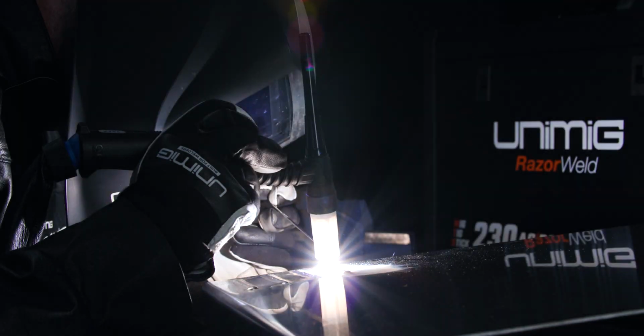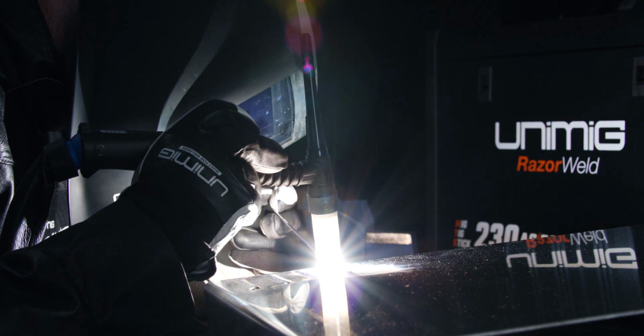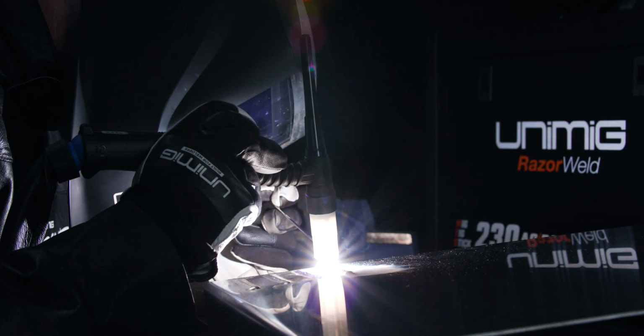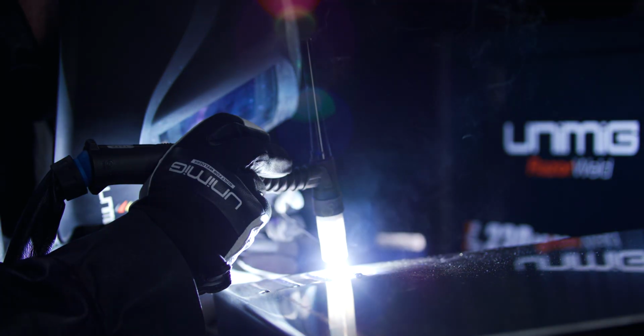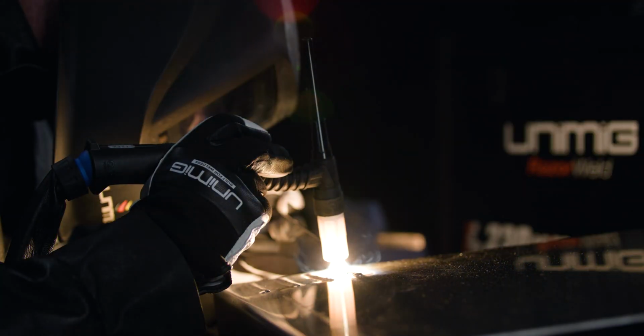Spot mode will produce a series of consecutive and evenly timed arcs, perfect for even tacks and small welds. When in spot mode, you can select how long you want the arc to be on. When the trigger is pressed, the torch will only weld for the set amount of time.